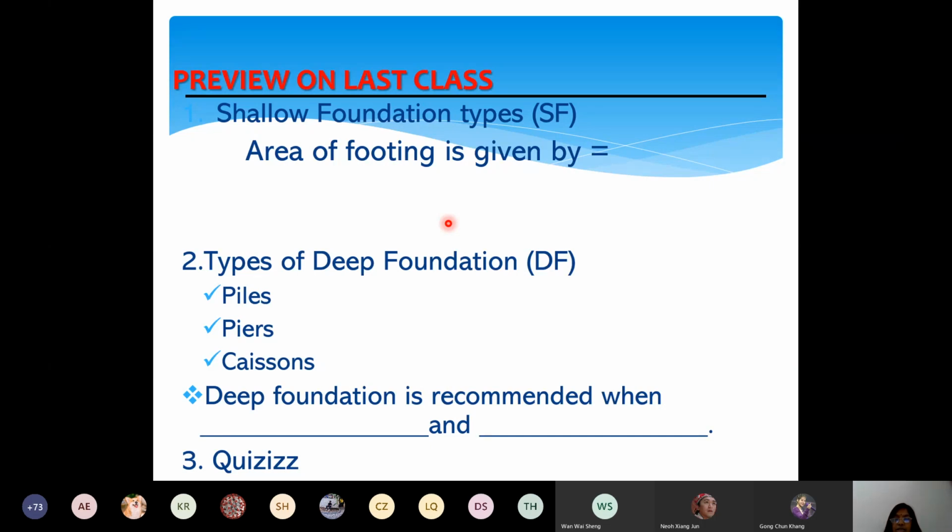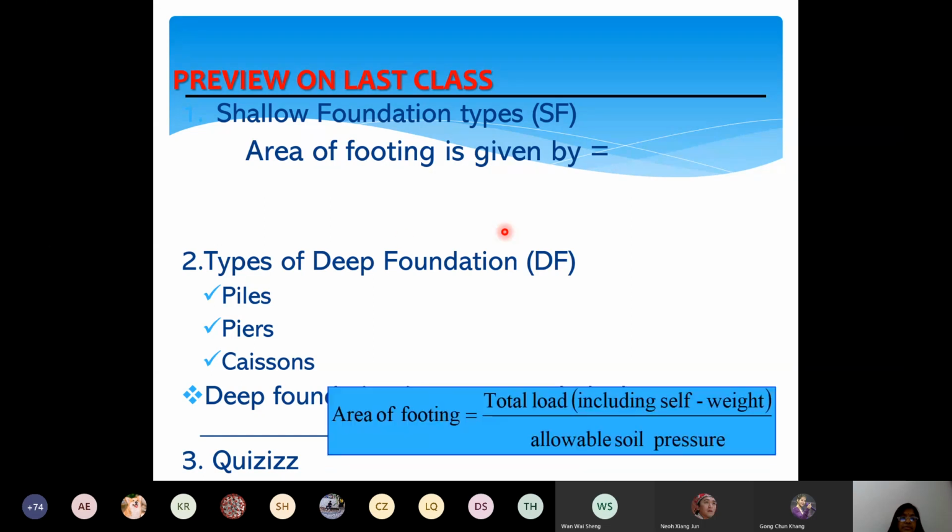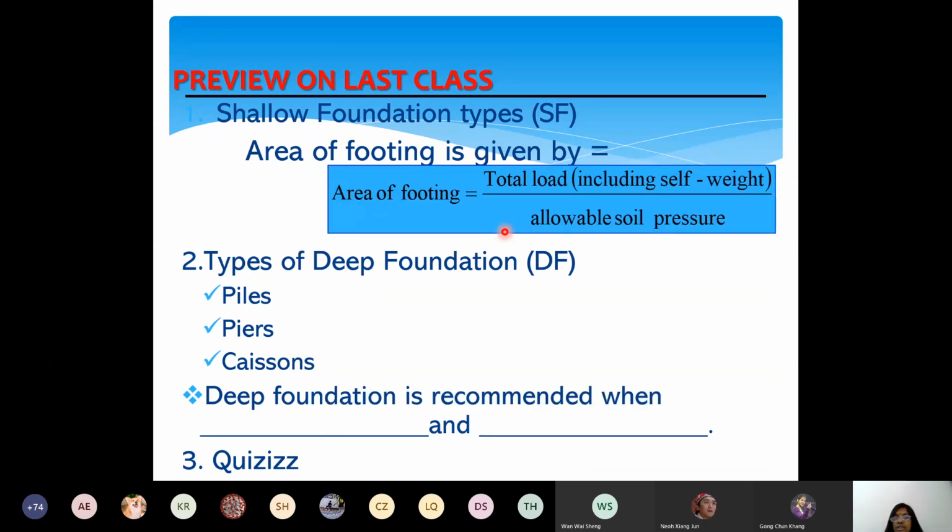If the construction is on poor soil, or the building is sitting on flood prone areas, then you have to go for all types of loading checks, right? So the simple definition: total load, including self weight, includes all types of loading coming over the building, over the allowable soil pressure or bearing capacity of the soil. Bearing capacity of soil, you can take a sample and test it to know how much kilonewton it can bear per meter square. It depends on what you are comparing with, right?